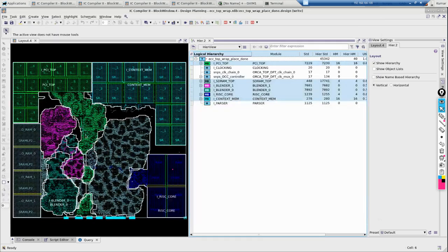Ideally, you are actually supposed to reduce your design size. So 47 is something that I don't accept. Since we are done with placement, it should be somewhere around 65 percent. Now why I say that, and what is going to happen if you have more area, we will discuss all of that when we get into that particular topic.